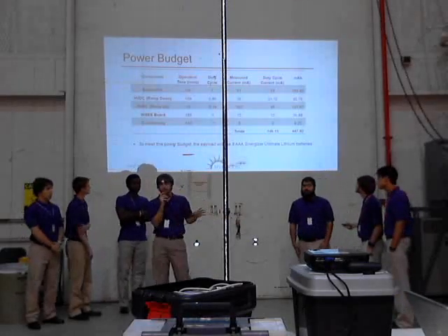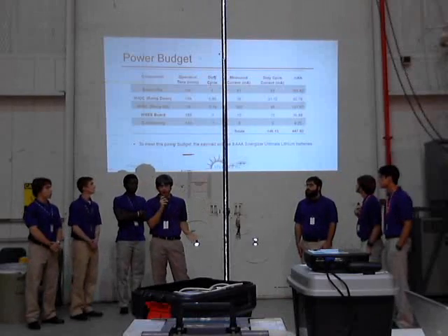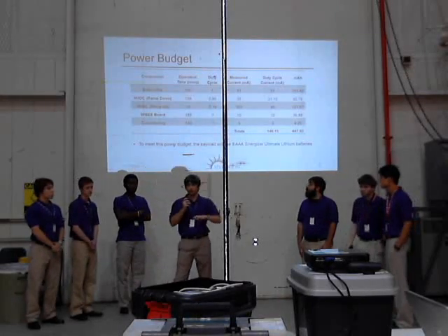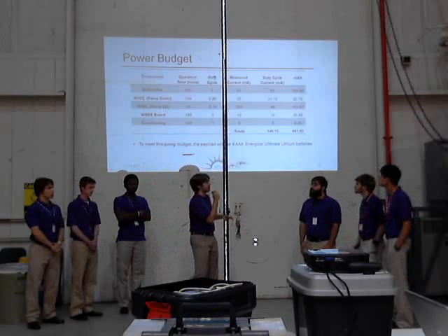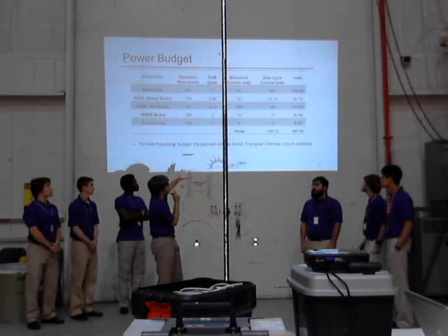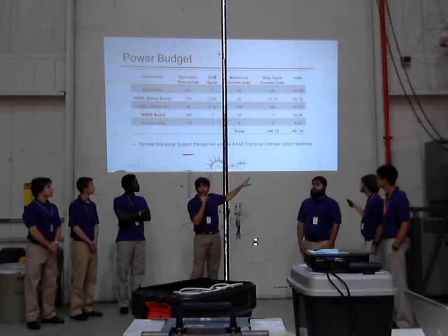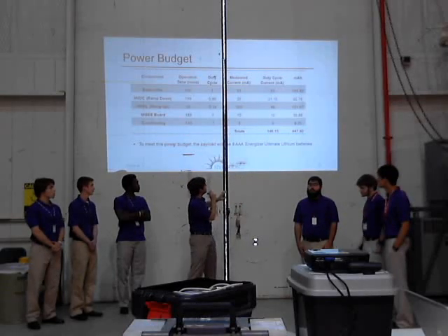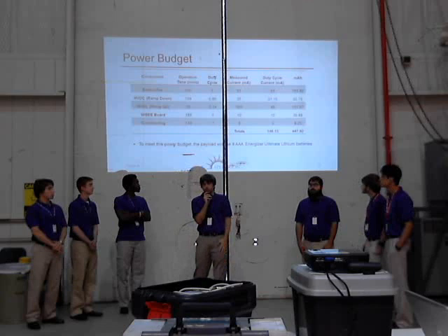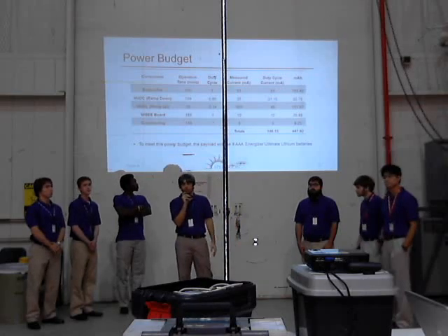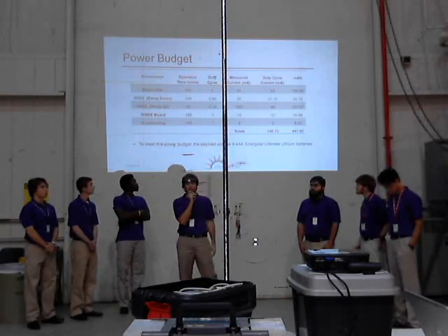However, the HVDC has two different cycles, when it's ramping up the voltage and when it's sparking, and when it's not doing anything. So those duty cycles are different. When you factor that in, we come out with a total needed milliamp hours of 447.92, which, using 8 AAA Energizer lithium batteries, more than meets this power requirement for our payload.